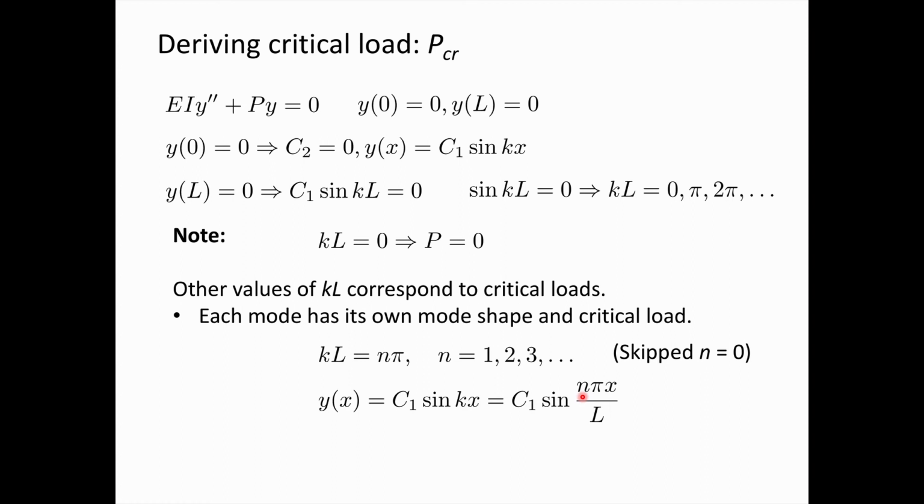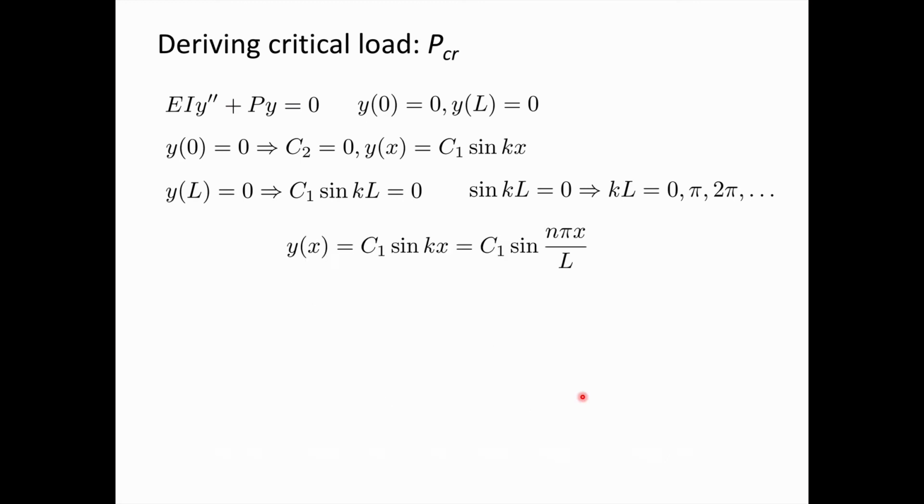We are interested really only in the loads, or the situations, that are going to occur in practice. And so if we are getting the column into a curved deflected shape by applying a load to it, not by prescribing its shape first, then really it's only the first mode that's going to matter. So it's basically going to look like a half sine wave. So it's only this first mode, n equals 1, that matters in practice.